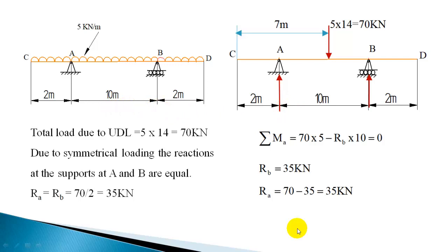Now let us calculate the shear force. But the shear force you have to calculate for the UDL. You cannot draw the shear force diagram for this acting as a point load, as that will produce a different shear force diagram and bending moment diagram. So you should not draw the bending moment diagram or shear force diagram by keeping it as a point load.